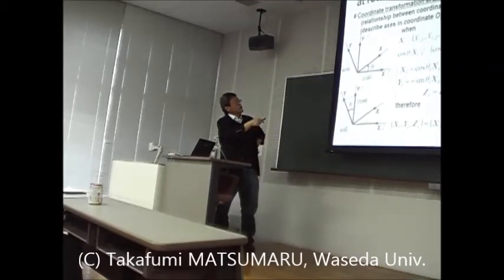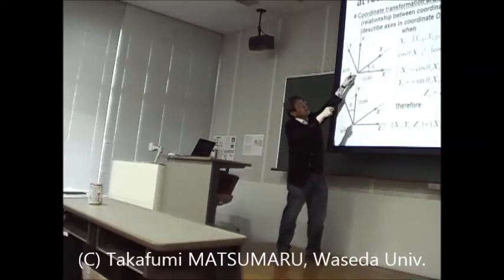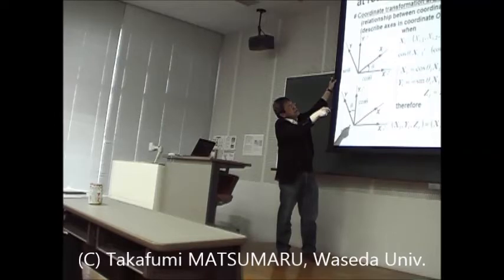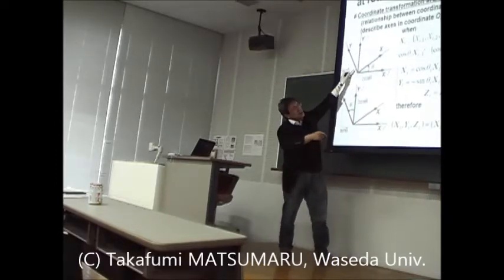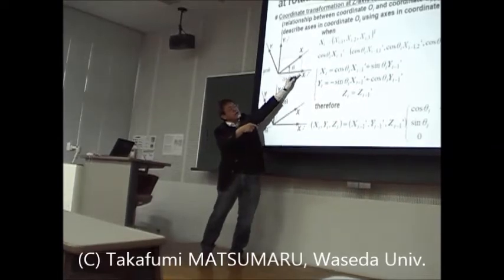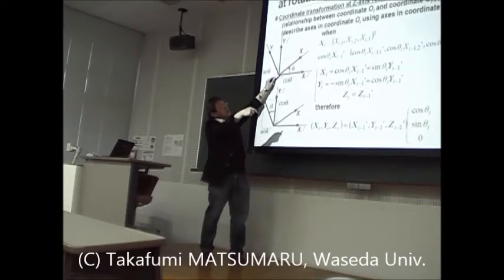So what we want to know is how the new x unit vector is produced from x_{i-1} and y_{i-1}. This vector x_i is this part plus this part: the x-along vector of x_{i-1} plus this vector. So here it is, cosine theta_i times the x_{i-1} vector plus sine theta_i times the y_{i-1} vector; this is the size of this vector, and this is the size of this vector.